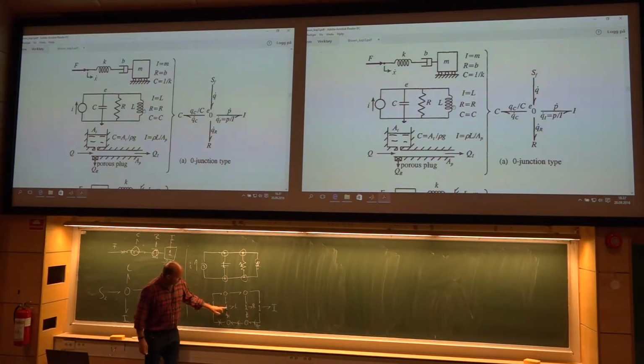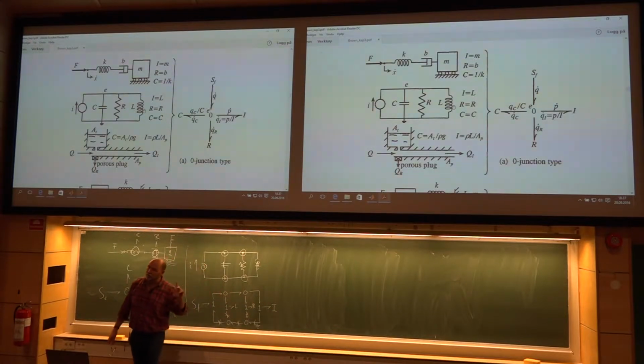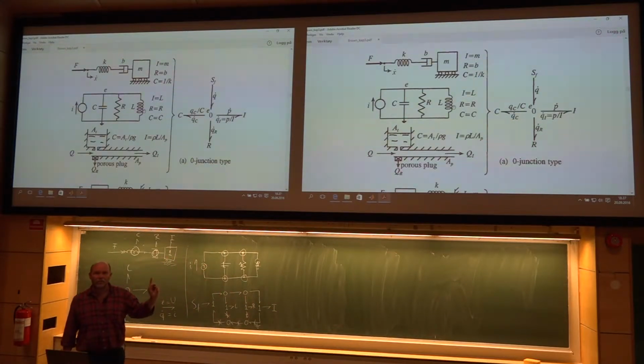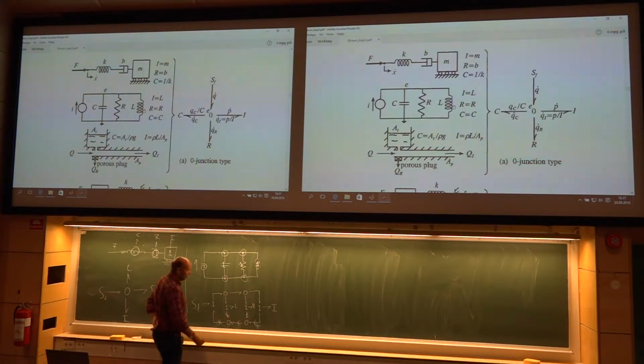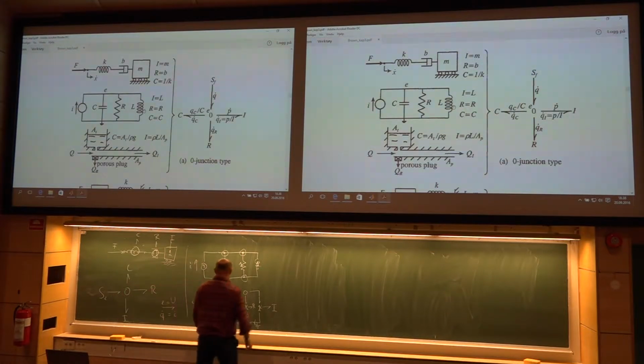Then these 1 junctions here, they have only 2 bonds. Any junction with only 2 bonds, well, then it's not a junction anymore. Then you can remove it. Remove this one, and this one, and this one. Then it should be a little bit better. Here we have 2 zeros next to each other. Join them. So we are removing that one. Let's see, for this 1 junction, now also only 2 bonds. Remove it. What are we left with?